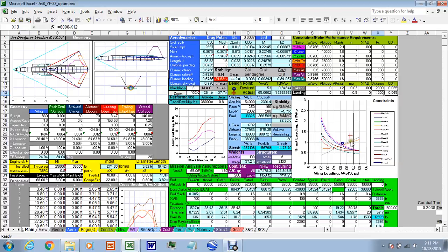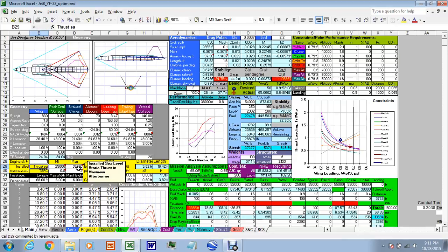Now there's a couple things we notice here. The aircraft has a lot more thrust to weight ratio than the optimum. And I'm wondering at this point if we can get away with one engine. That'd be remarkable if we could. So let's give it a try. Let's try one engine, put a 1 in here, and yeah, we're not meeting anything yet. But look, by taking away the engine, we took away a lot of weight, and we now have 12,000 pounds of gas we don't need. So we can drop the weight by 12,000 pounds to 42,000.